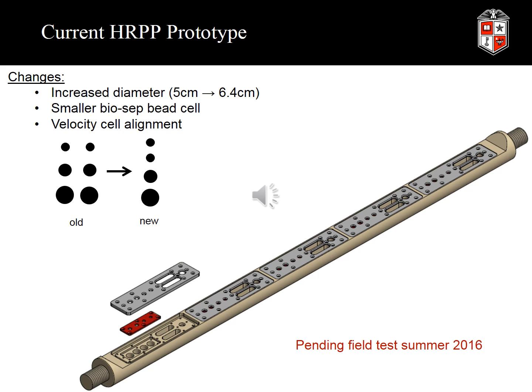So from the results of our first field test, we learned quite a bit about how the samplers work, and we were able to make some improvements and design a second version prototype. We increased the diameter of the sampler to 2.5 inches. We did this because in general we will probably core before inserting the samplers. The reason we core first is not that we have to get it in the ground, but we don't want to cause secondary impacts from compression around the sampler. By coring we reduce the compaction that occurs.